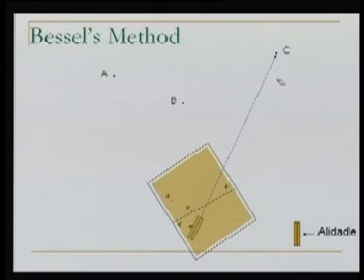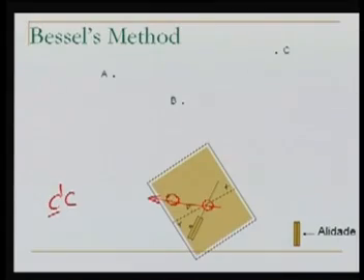Now the intersection of XY and this resector gives us a point C dash. Okay, that point is C dash. So once we have this point C dash, we keep the alidade along C dash C. So we keep the alidade like this, and now again we unclamp the table, because we have to follow these steps very carefully. We are unclamping the table now, keeping the alidade along C dash C.